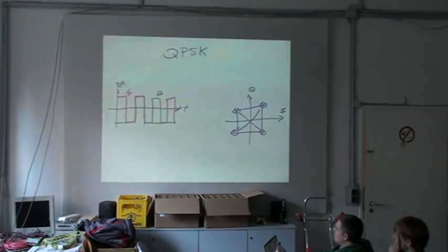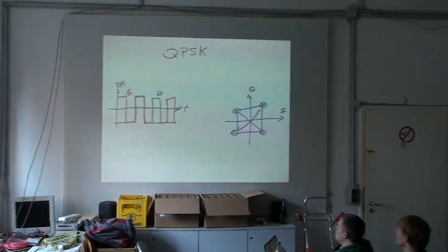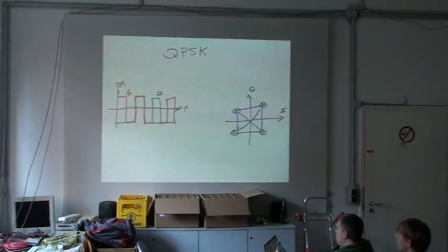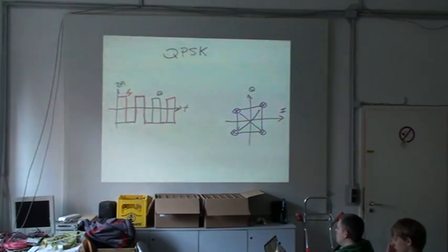So you have an in-phase symbol stream and a quadrature symbol stream, and if you look at the in-phase and quadrature components on a two-dimensional plot, what you see are these 4 points that represent the states that the signal occupies at the middle of each symbol period, and then these other lines represent the possible transitions. This type of plot is called a constellation plot, and it's a pretty common way to express the structure of modulation when you're working in this problem space.